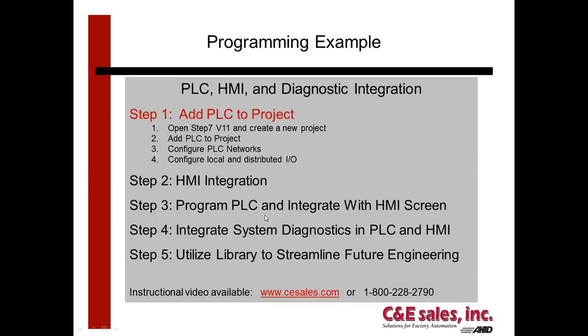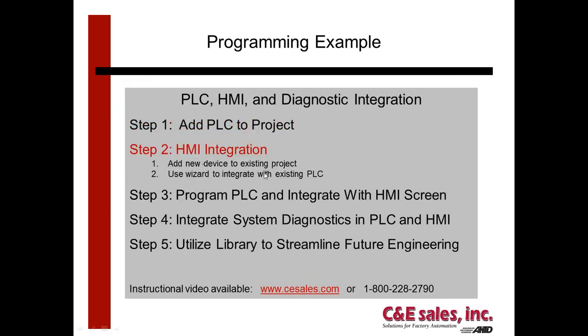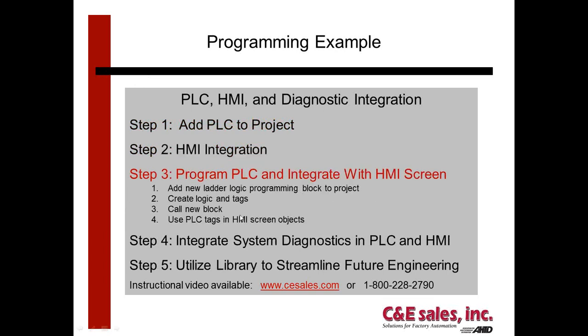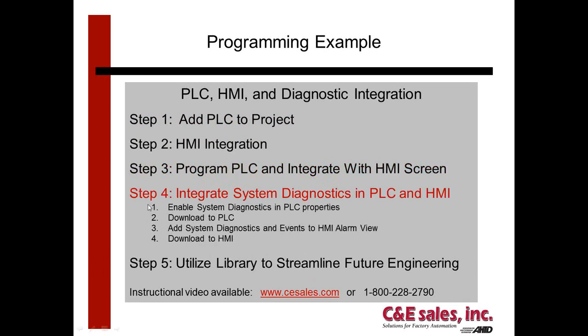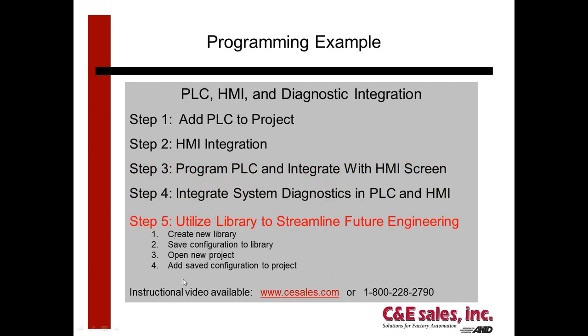And this is a little snapshot of what we're going to do. We're going to add a PLC to a project, add an HMI and integrate it with the PLC, create a very small PLC program, integrate that with the HMI, and then show the system diagnostics that I just mentioned. And then one more feature that I didn't touch upon, and that is the library functionality. Show how we can create a library and take any object in our program, whether it's configuration or programming, drag it into a library and use it in a future project.